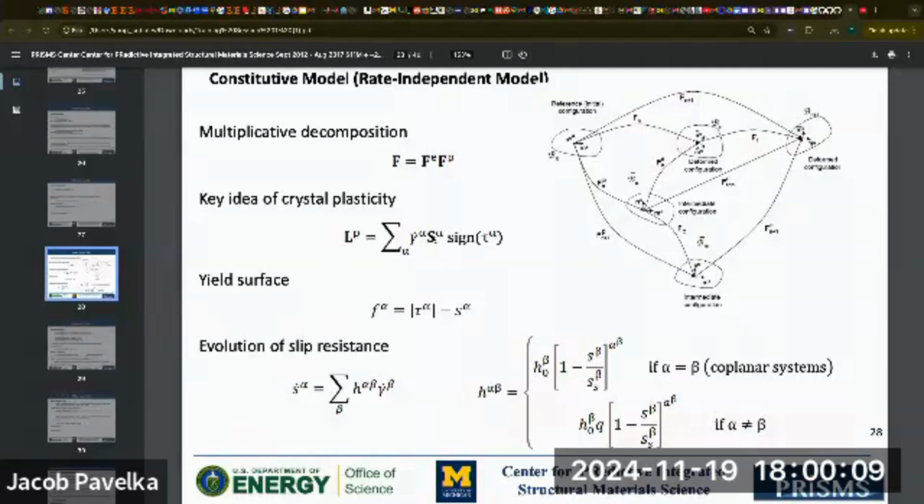Essentially, we define all these slip systems, and they have some thermodynamic conditions for whether they'll slip or not and the rate at which they'll slip. We calculate those things and put them into this L_p, which is some projection of this stretching. It solves all these things, and then you accumulate all your plastic deformations in addition to your elastic deformations. You do that at every time step. You track the state of all these slip systems at every material point in the mesh. That's it, basically.